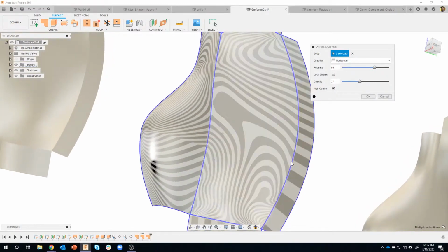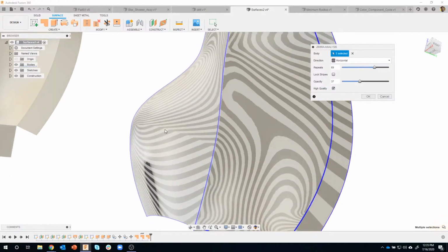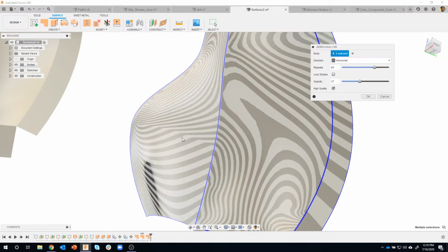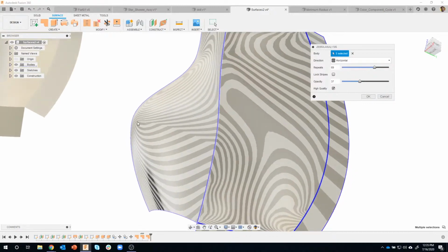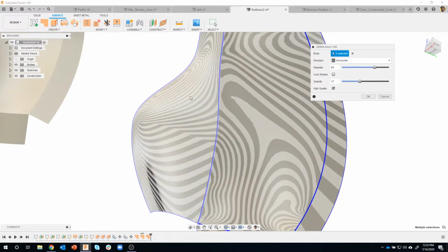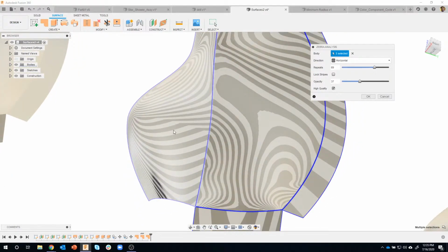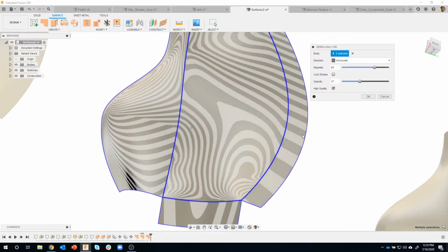Now here's something interesting. As I did that, I'm starting to see something kind of weird right here. Instead of nice, smooth, curved lines, it kind of comes to a sharp angle. So I could probably tell that there's something wrong with this surface here that I might want to go back and tweak. You know, and this was a loft, I think, is what I used to create this. So there might be something going on with one of my loft lines. And so I can visually see that that could potentially show up when we manufacture the part.